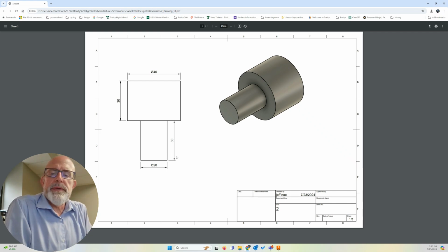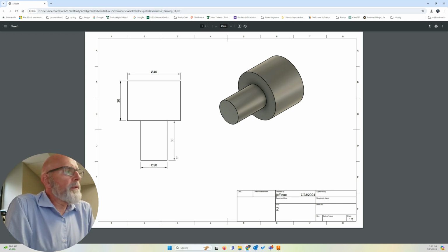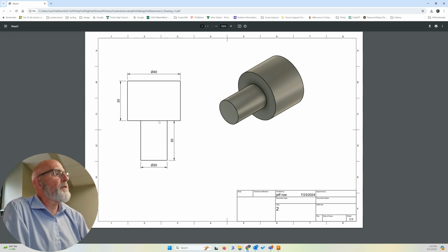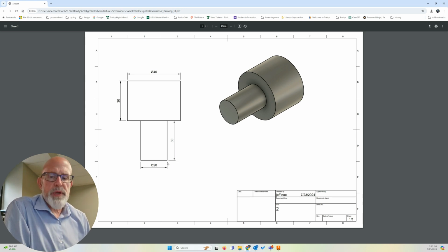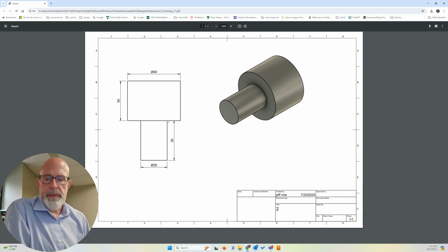Maybe we could draw a rectangle 10 millimeters wide from the center of the post here, up 30 millimeters over and revolve it. It seems like a backwards way of doing things, but I guess it's possible if you wanted to draw rectangles. So let's just be conscious of that. Match the two things up. This is why this image is provided, to give you more information that you may infer from looking at this, that this is not a square. It is round.